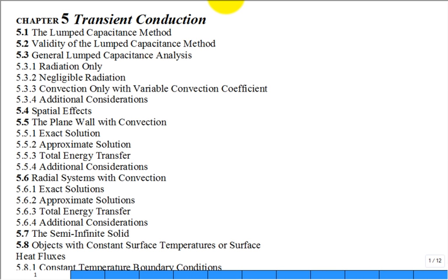So we had the heat diffusion equation. Can you recall the heat diffusion equation? Something like, I don't know, del squared T plus, you can put the k there, q dot over k, equal to rho c over k times the rate of change of T with respect to time. So this was our diffusion heat conduction part, the Laplacian of temperature.